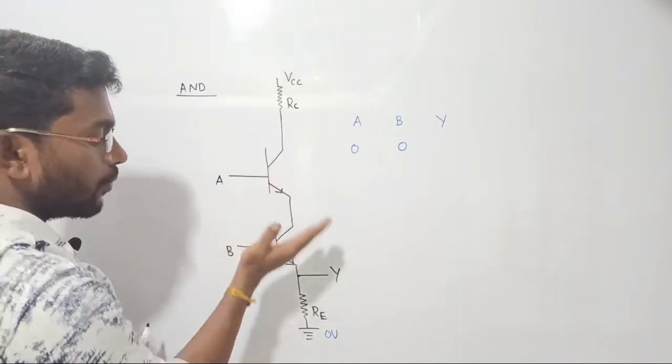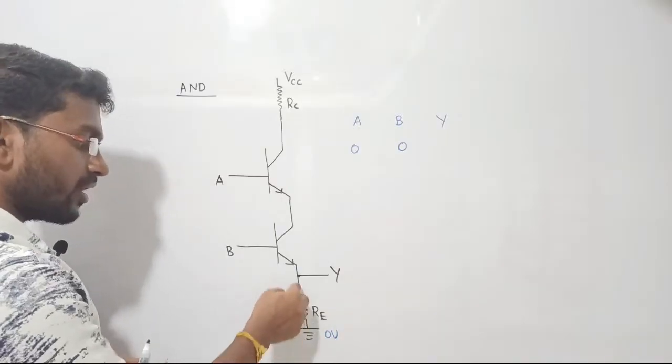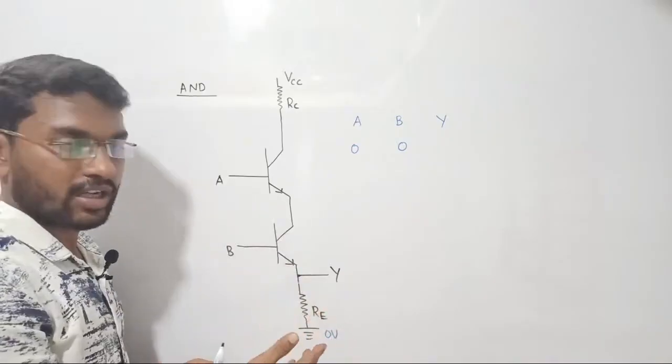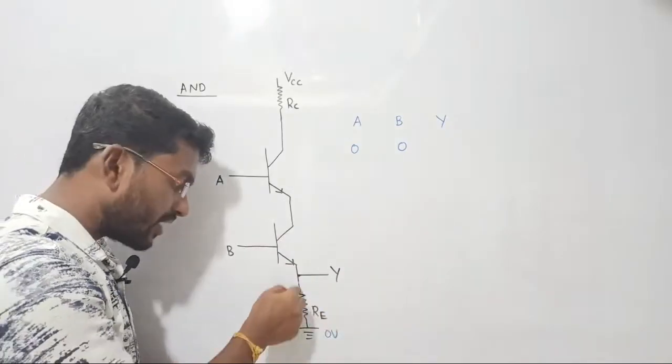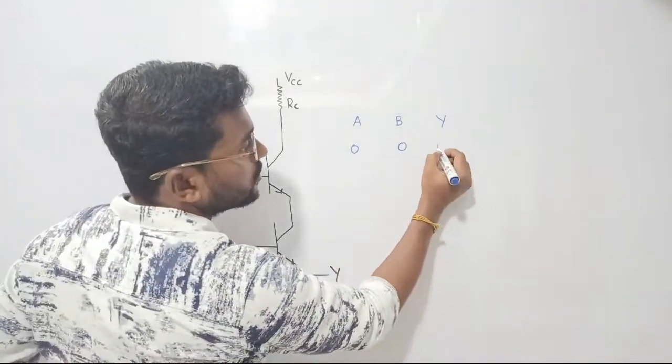These transistors are open. So there is nothing here, nothing up to here. Directly there is ground here, and there is a terminal here, that's all. So what will happen to this zero voltage? Automatically it will be reflected. See, since both are open circuit, there will be no current flow in an open circuit. So this resistor will become a useless resistor. So this zero voltage will be reflected such that output is going to be 0.